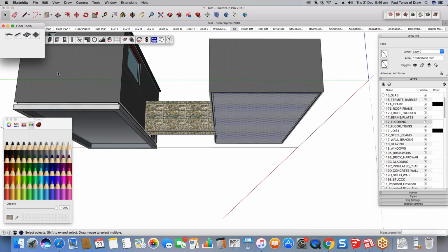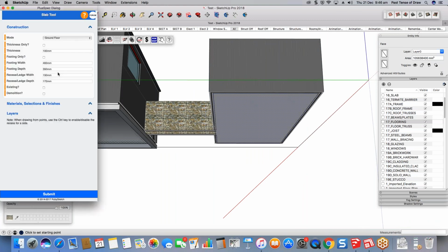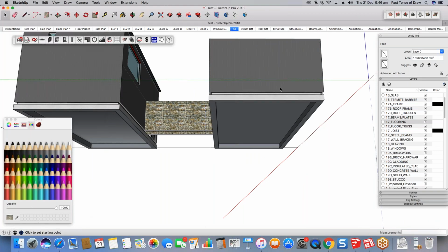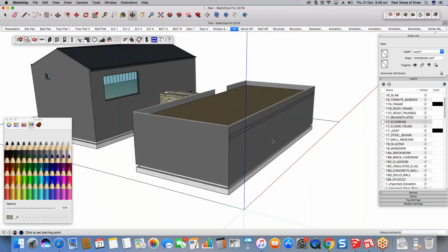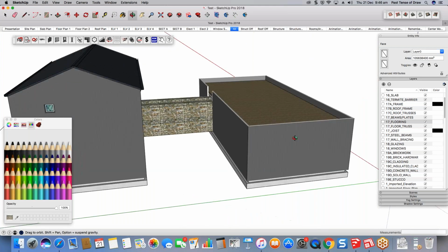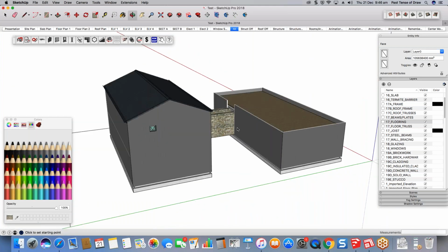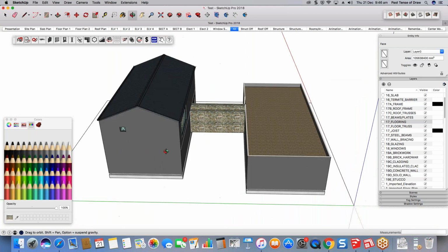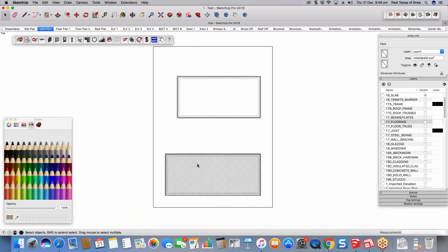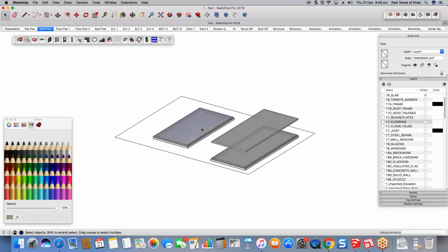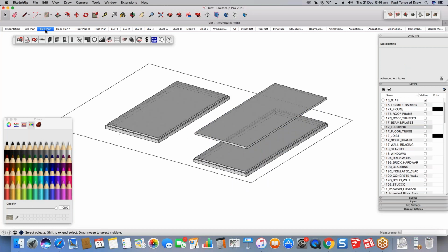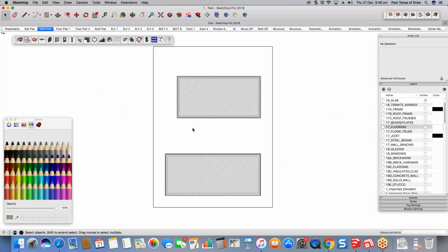So now what I'm trying to show you or trying to teach you is that you can bring your PlusSpec for SketchUp model into your 2D drawings quite early, knowing that whatever you do in the model is going to automatically update. So now if I go into my slab plan, you can see, yeah, that's working quite well. I can move over, I can delete. Sometimes the shape that you draw will be left there, so you can just delete those if you need to.